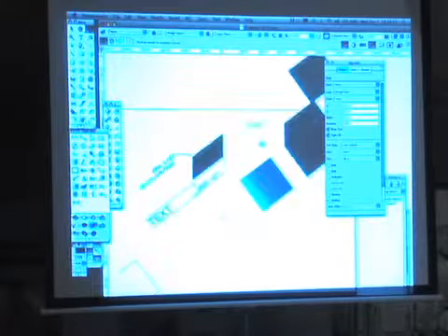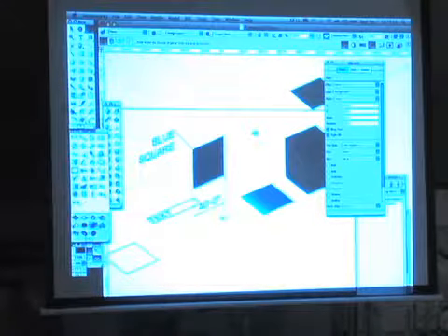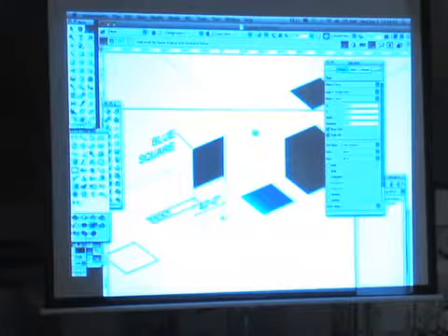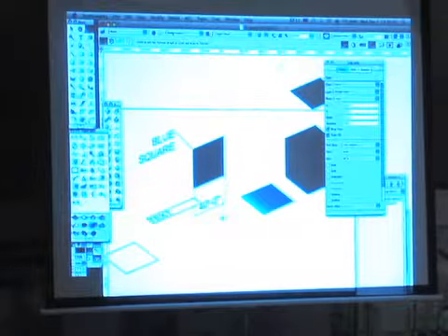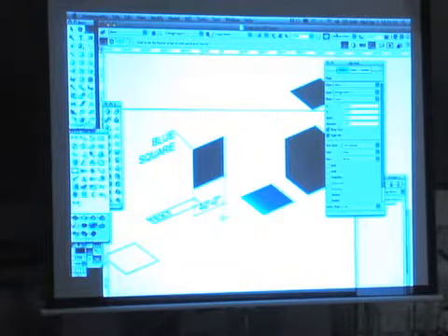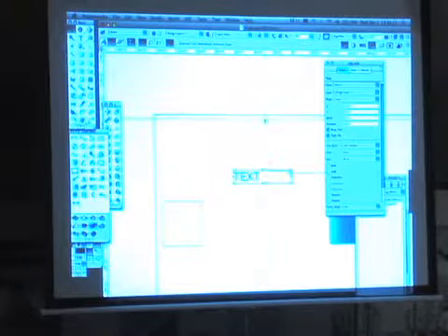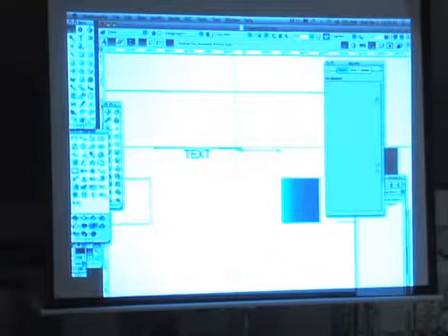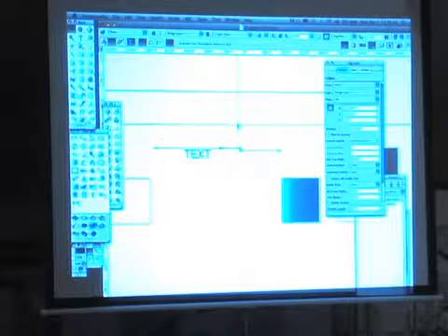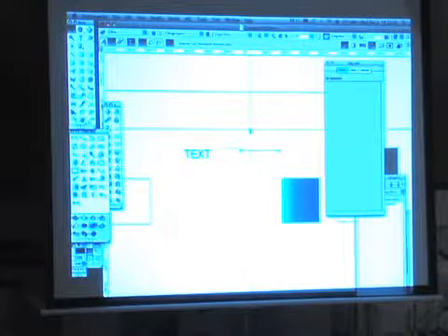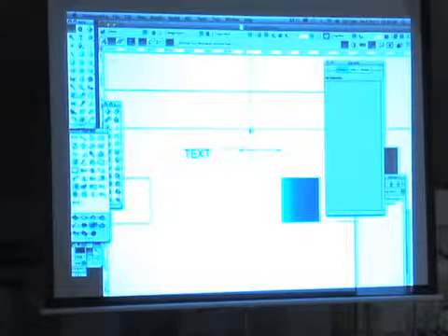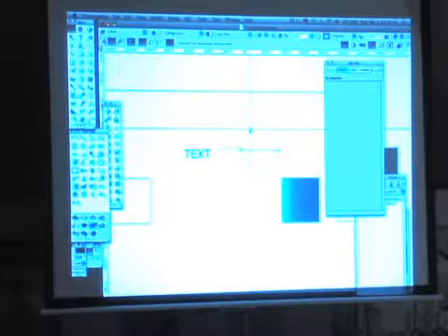But now it behaves a lot more like SketchUp, where you can do dimensions and annotations in a 3D model and have them stay true to the working plane. Now, does all that disappear when you go to top view? Is that rectangle just a line? The rectangle will just become a line. You see it here, there's the block of text, sort of not quite on it. So yeah, it still changes the orientation depending upon which view you're looking at it from.